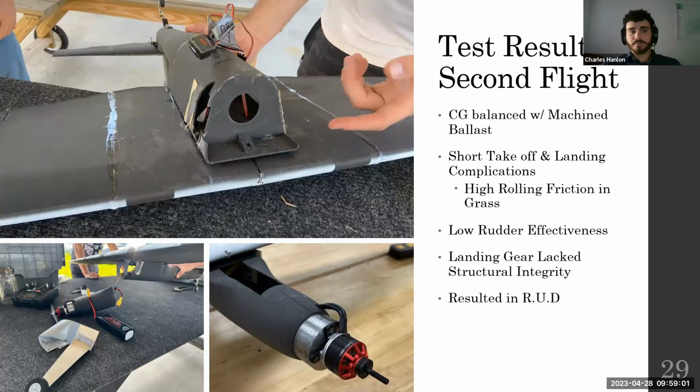In order to fix the problems we experienced on our first test flight, we had to add a machined ballast to the nose of our aircraft to get the center of gravity underneath the center of pressure of our wing. After this was done, a short takeoff and landing was attempted, in which we experienced a veering to the left due to improper rudder control and landed in the grass, experiencing high rolling friction, causing the nose of the plane to dive into the ground, causing it to snap off. This was due to the fact that the lightweight PLA was not meant to withstand these forces.